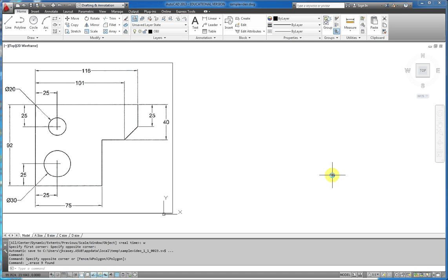Okay, so in chapter 1 you learned about XY coordinate values, absolute values from the origin, and also relative values with relation to the current location. You also looked at polar coordinates, which you would give a distance and less than some angle. So those are all really important fundamentals to understand, but in AutoCAD we really don't draw features that way.